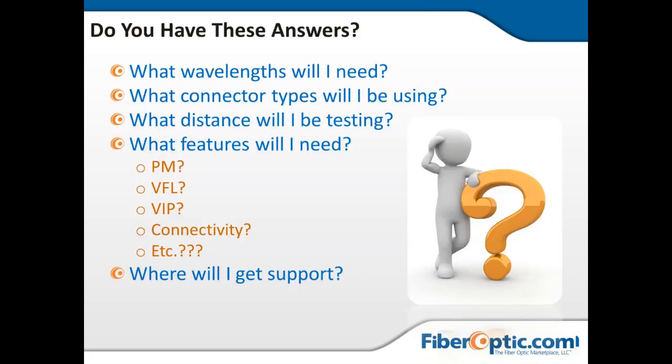There's a couple reasons why, and again we'll get into that: damaging the front end of the connector, being able to see the first connector to make sure you have an effective connection, and things of that nature. But you will need to know that if you don't have a launch box that has the appropriate connector and mating sleeve, then maybe you have to connect directly just to test continuity or get some sort of basic reading.